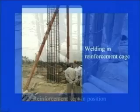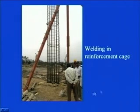Why it is done will be clear in this one. You see here, this is the bamboo with the help of which the reinforcement has been kept in position, and you can see this particular labor is welding here. Up till this point there was one reinforcement cage, and most of the portion has been lowered into the borehole. However, with the help of this rig, another reinforcement cage has been lowered to the extent that this worker is welding it.